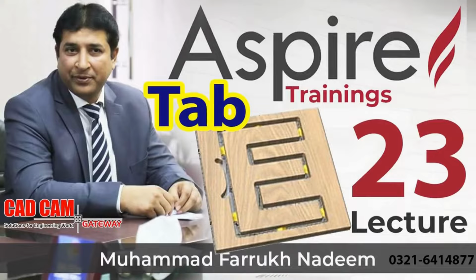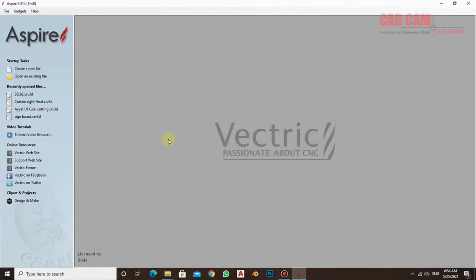In today's tutorial, we will learn how to cut some words. Last time when you learned how to cut words, basically we did their nesting. But in this lecture, when we cut some Arabic words, we have to remove them from the sheet in a safe manner. Normally the common issue that comes up when we are cutting is that due to the pressure of the cutting tool, the words break apart, or when they come out quickly because of air pressure or the cutter's pressure, they get damaged as the cutter moves forward, or sometimes the cutter itself breaks or the words break. So how do we save them? What is the proper method for this?